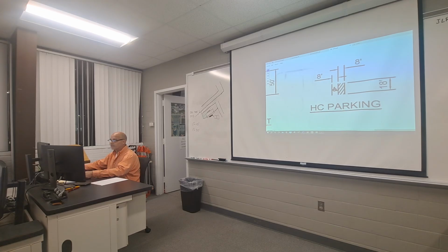Does that count for 2 parking spots? No, that's just one. That is all one handicap parking space. Are you gonna give us a specific amount of handicap spaces? Yeah, I'm just going to tell you, don't put a handicap on the other side and just use that one hatched area in between them and count that as 2, because this one on this side still needs that hatched area for the van accessible. So it's always on the right or passenger side of the vehicle.